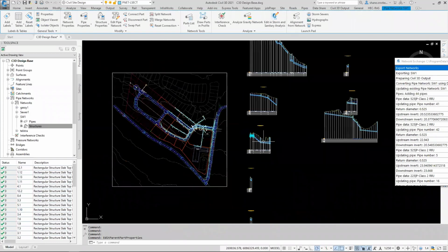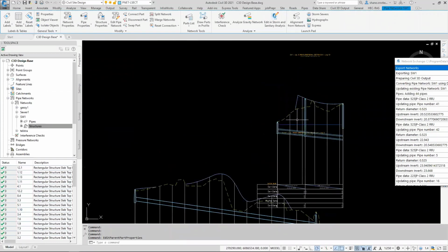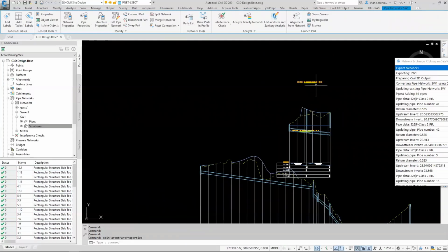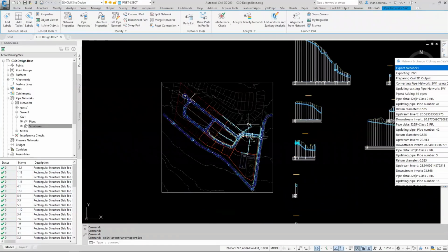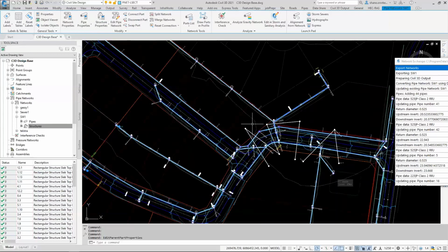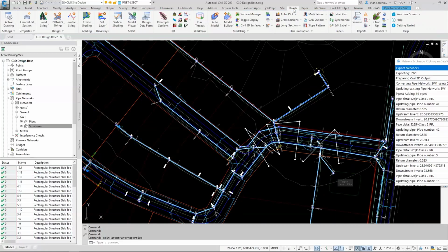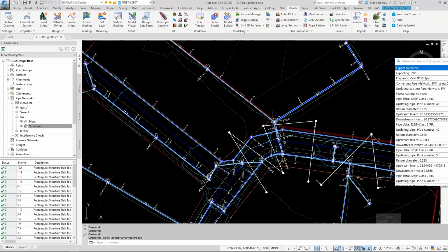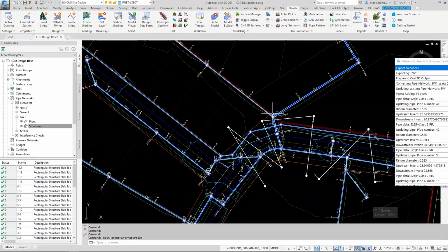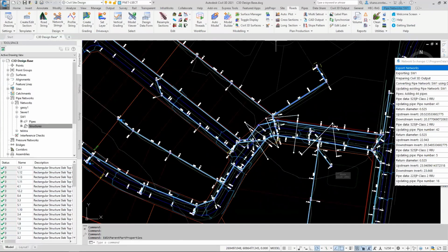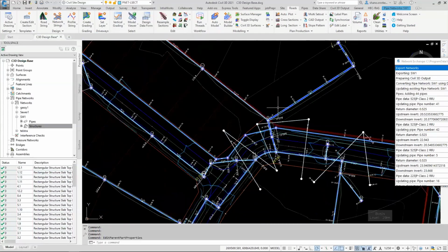There are a few questions about showing the solids in Model Viewer, and Shane showed a method. There's two methods, and the method that Shane showed is great. However, with Civil 3D networks, you can come up with some really quite detailed looking parts for the pits and even different types of pipes rather than just being circular. So what you can do is export the pipe network to solids.